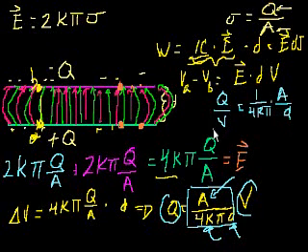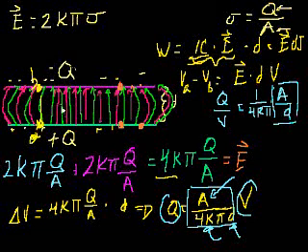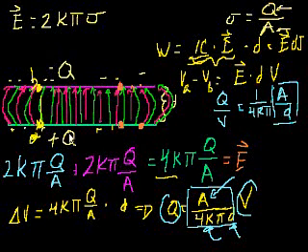So what it essentially says is, for a given configuration, and the configuration is defined by the area of the plates and the distance, if I know the amount of charge that I put onto the plates, if I did a minus Q here and a plus Q here, I know the voltage across the plates, or vice versa. If I know the voltage across the plates and I know its configuration, I know how much charge there is. And this is called capacitance.